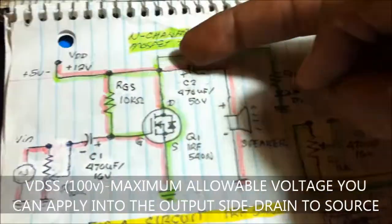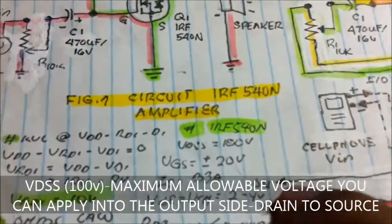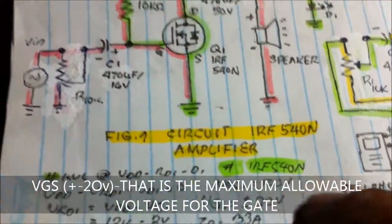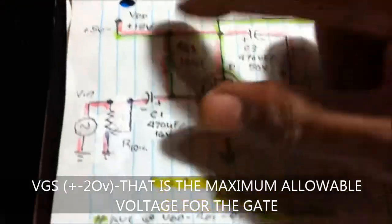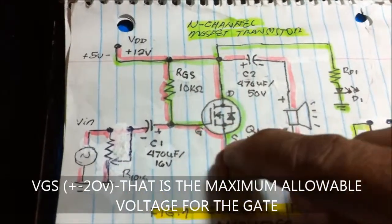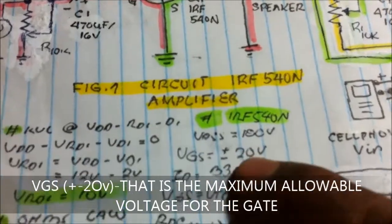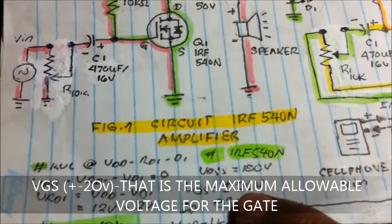Means this voltage 20 to 100 volts. Very big. And what is this VGS? Positive, negative 20 volts. Voltage at the gate to source. VGS is the maximum voltage you can apply to the gate to the source. Since this voltage supply, the maximum is positive 20 and negative 20. Why positive 20, negative 20?